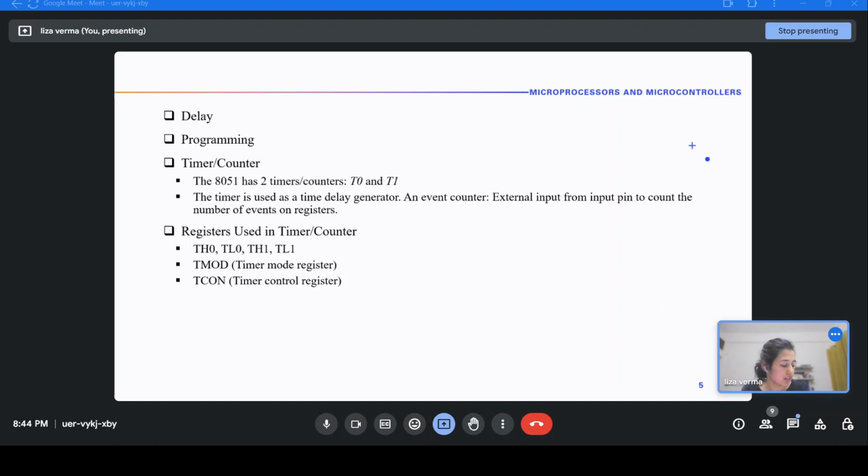So the question remains: timer 0 is completely occupied, right? TL0 has become one timer, TH0 has become another timer. Timer overflows of both timer 1 and timer 0 are occupied. What is timer 1 doing?